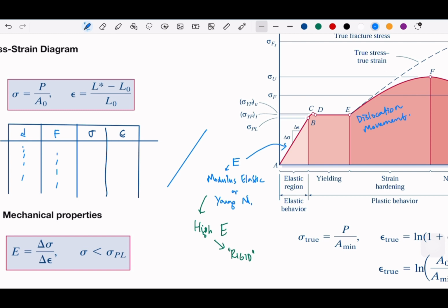But what it means is when we pull the material, we give forces. Imagine all the atoms, all the crystals are going to take the same force. Remember, we have learned that the forces are distributed along the material, right? What happens when we have the defect is the defect also moves. So when the defect is moving, it actually starts to have this plastic behavior. And at the same time, the movement of the dislocations will make the whole system become hardened.